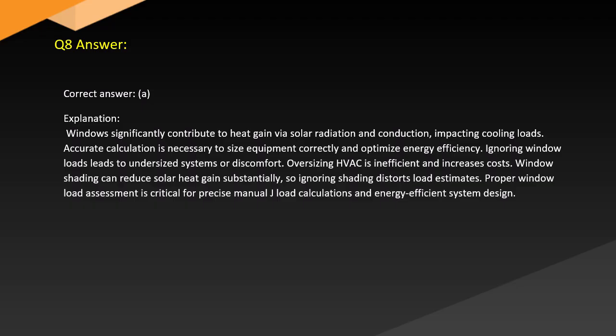Answer. Correct answer: A. Explanation. Windows significantly contribute to heat gain via solar radiation and conduction, impacting cooling loads. Accurate calculation is necessary to size equipment correctly and optimize energy efficiency. Ignoring window loads leads to undersized systems or discomfort. Oversizing HVAC is inefficient and increases costs.